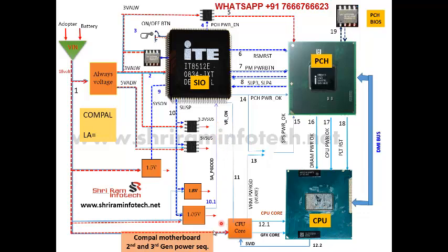Now, SA, where will it come from? SA power good comes from this section, to these chips and all the pins. The regulators generate the power good, and this power good is very important. What is it? 1.05 volt. That is the system voltage to the CPU and PCH.